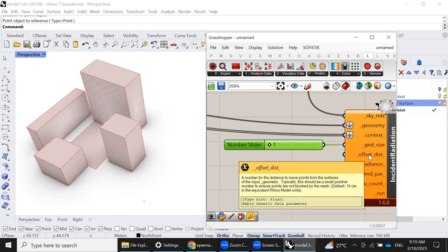In the first few lessons where we were beginning to do the Esplanade tutorial, we were sharing with you how sometimes your sunshades will face downwards because of the way in which you have modeled the surface, and which is also because of the way that your U and V maps are being done. Similarly, this offset distance is going to be oriented according to where your normal is.